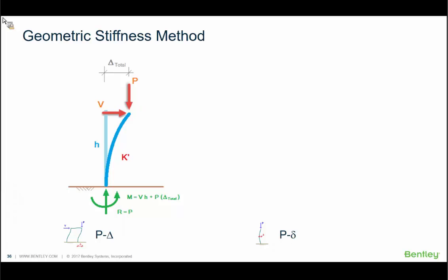Using these reduced stiffnesses, a single analysis, rather than a succession of analyses, produces the design deflections and the member forces. Theoretically, this approach gives identical results as the iterative method, but in practice, they're not exactly the same, but they are generally very, very close. Time doesn't permit a more in-depth discussion, but a web search should bring up more detailed information on this methodology. It should be noted that this method only accounts for large P-delta. It doesn't account for small P-delta. Small P-delta must be accounted for in some other way, such as by using, for example, the B1 amplification factor.